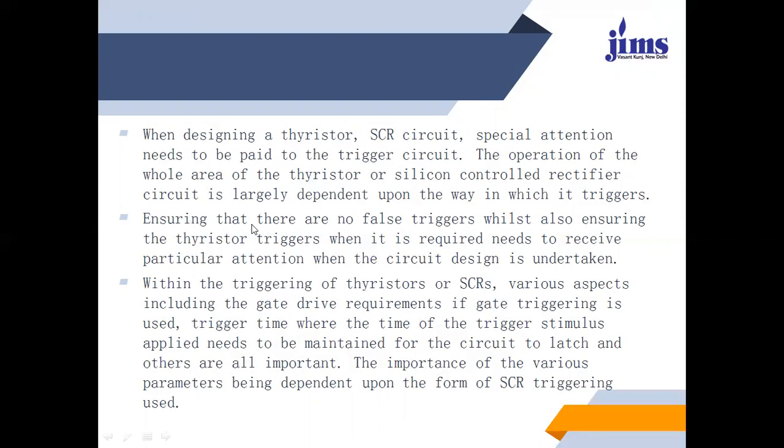Ensuring that there are no false triggers, while also ensuring the thyristor triggers when it is required, needs particular attention when the circuit design is undertaken. This is important: no false triggering signal should be given when we do not require the thyristor to be triggered.